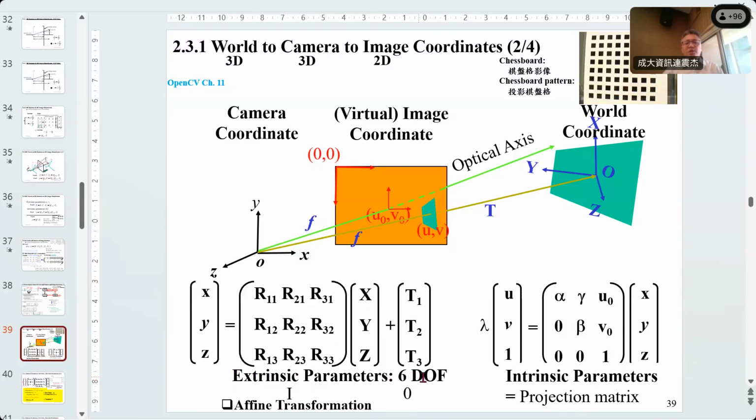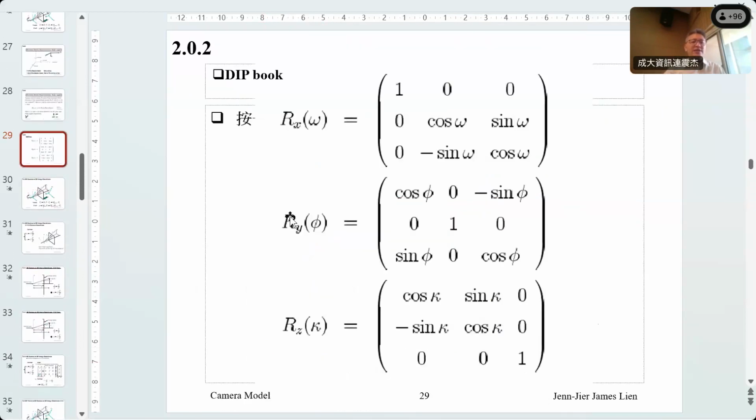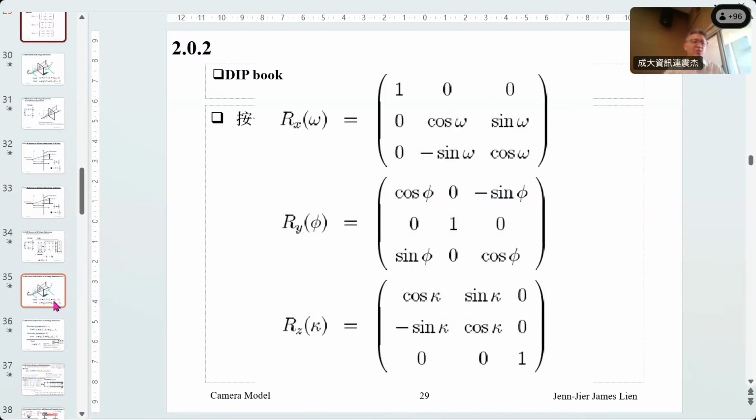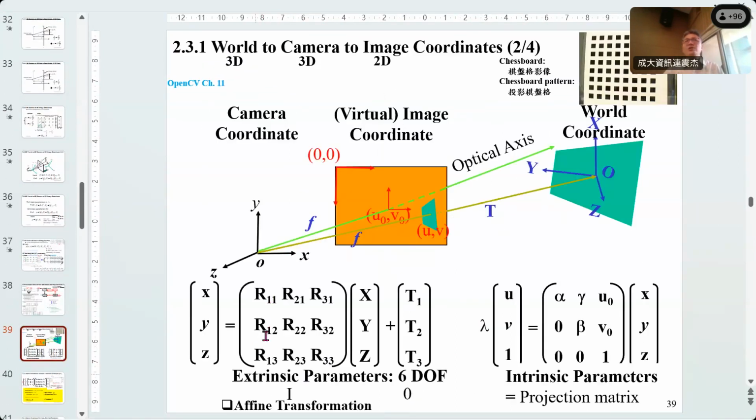And they have 6 degrees of freedom. What's degree of freedom? Degree of freedom means 自由度. Okay, so here we have Rx, Ry, Rz. So we have 3 degrees of freedom for rotation. Even though they have 9 components, we call this only Rx, Ry, Rz. Although it has 9 parameters, we will define each rotation later. Remember Rx is usually like this one. This is Rx, Ry, Rz, but here it is written in matrix form. Basically it has 3 unknowns for 3D, 2D would only have 2. Then the 3 translations are X, Y, Z.